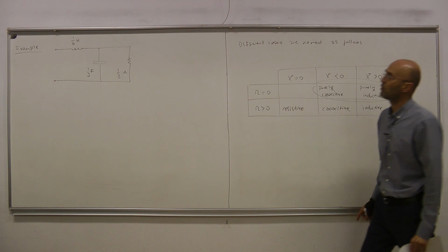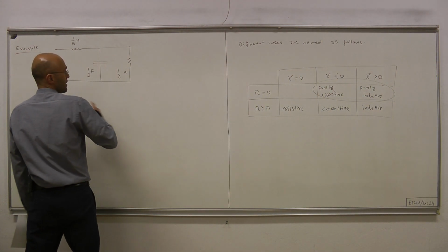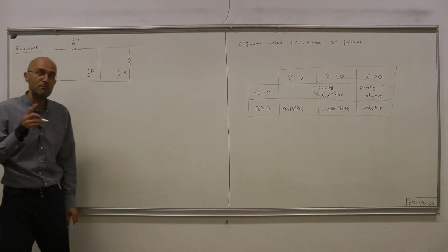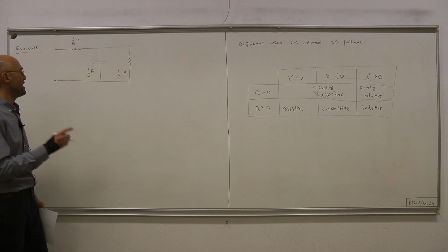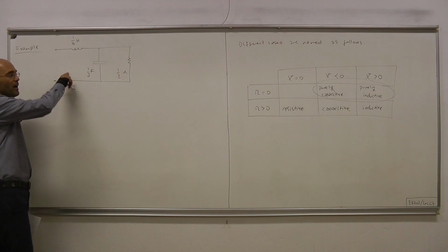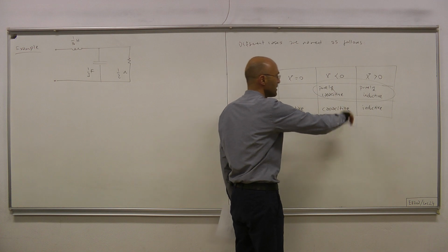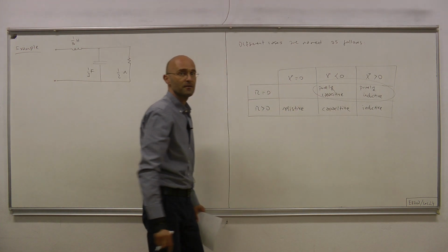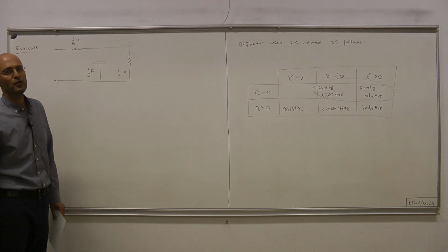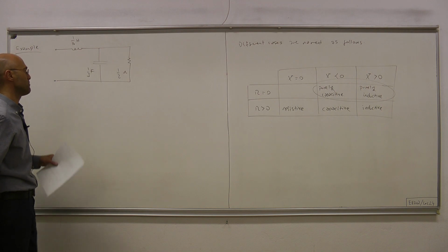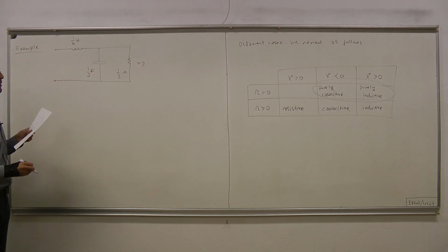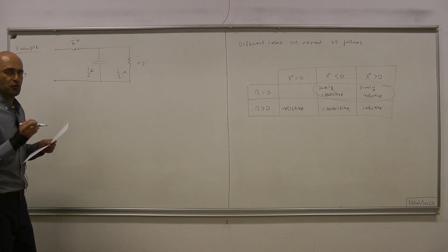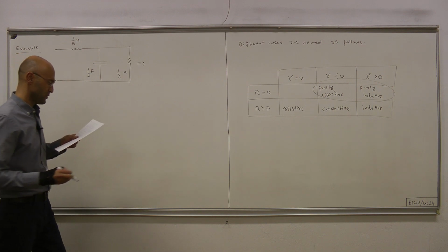Now, that's a premature question because this definition is based on impedance, and impedance depends on the frequency of oscillations. Hence, whether this one port is resistive, capacitive, inductive, or anything from this table depends on the operating frequency. So the answer will depend on frequency. So let's therefore obtain the impedance for this one port, and to do that we convert it to the phasor domain first.